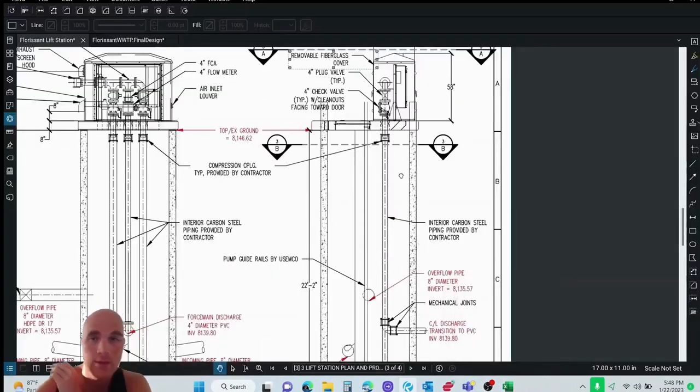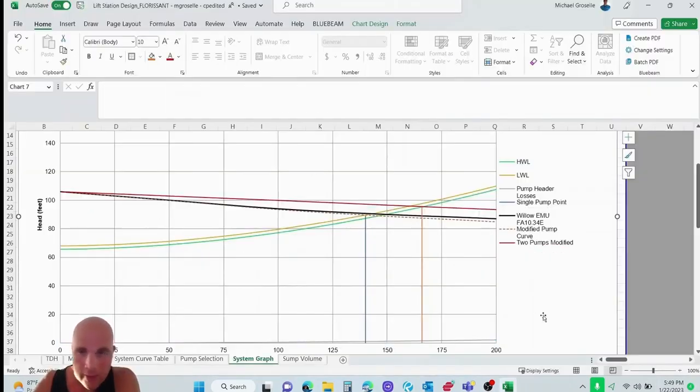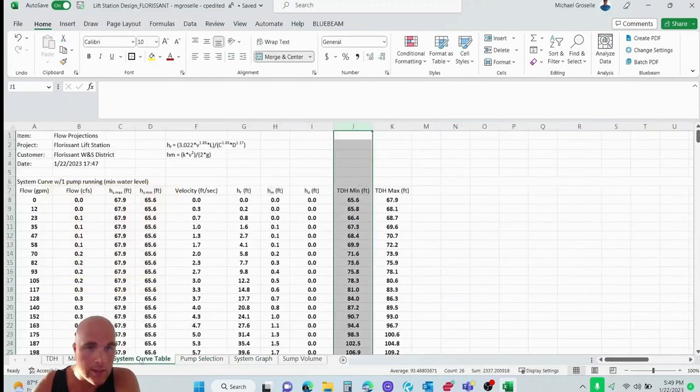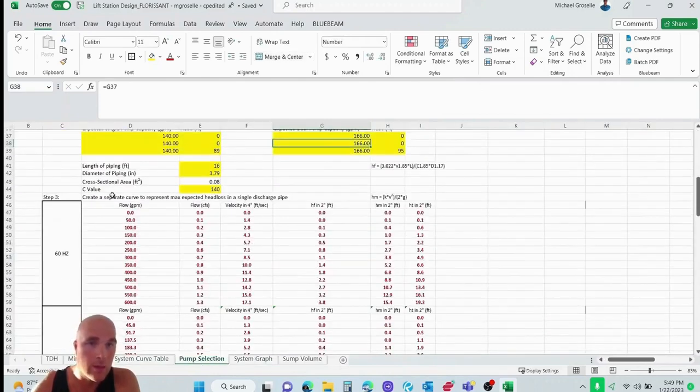It makes a big difference. But it's its own. Sometimes you can have 2-3 pumps pumping into one force main, but when you're adding up all the different pump heads, and if you have different sizes of pump, you'll want to do its own calculation on the side, and you'll see where we use that later. So that's this gray line down here. It's very small, and it's calculated in the pump selection table down here, where a different head loss is being calculated for each curve.